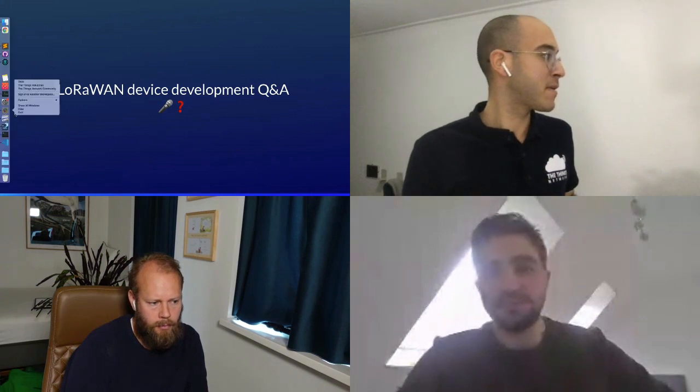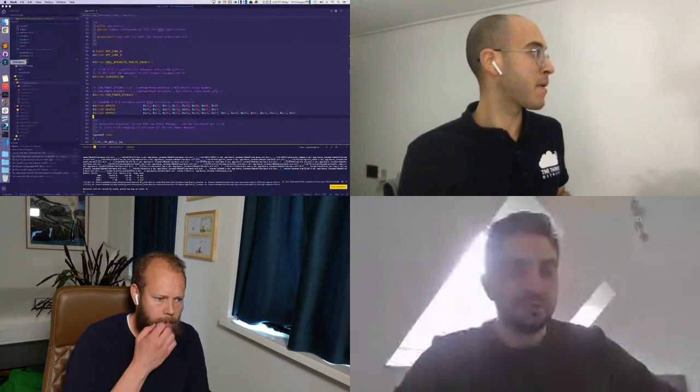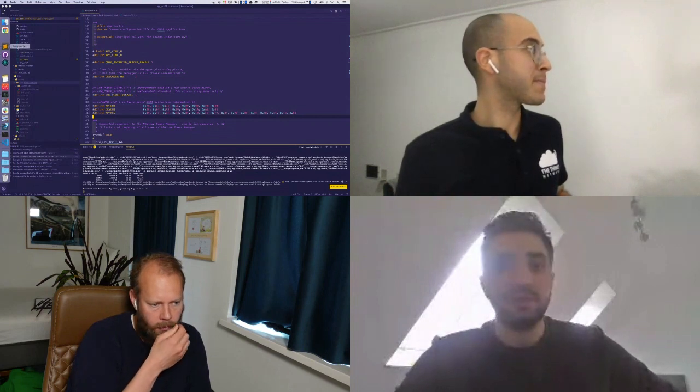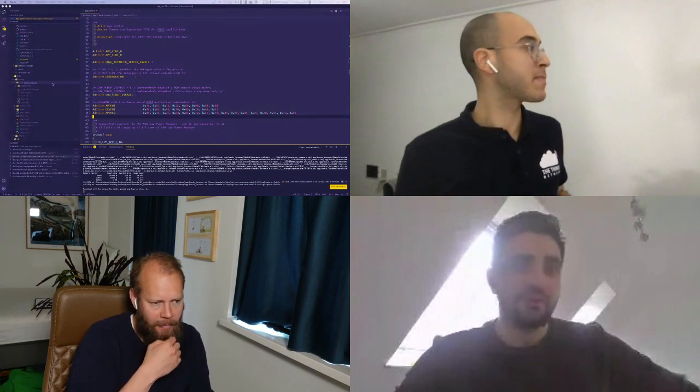Yeah, Orkhan, you're happy about that part? Yeah, yesterday we were a guest at the ARM Innovation Coffee, and we did a live demo there, and maybe we can later share the video link. Yeah, I can try to find it. For the LoRaWAN example, basically sending a packet every 10 seconds, in our example code the sleep mode current was around 1.9 microamps. But I believe it can go even lower than that.